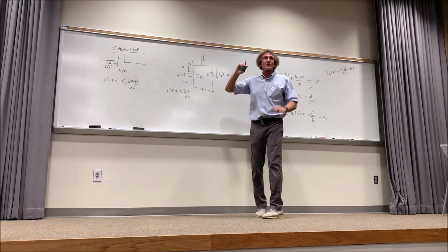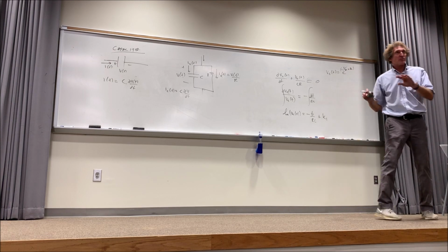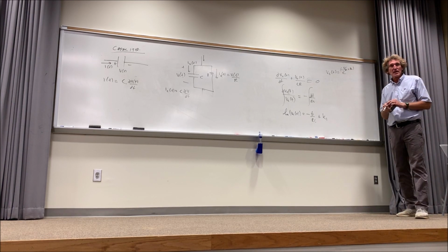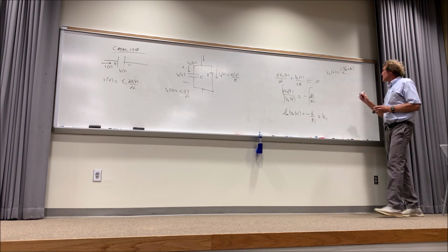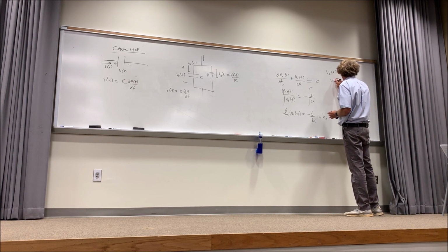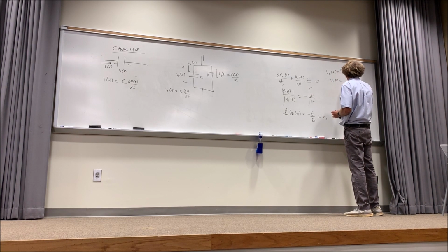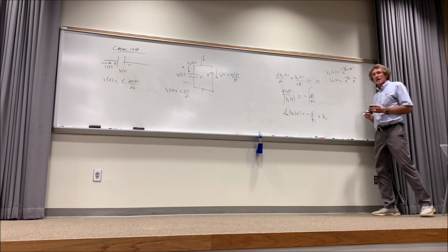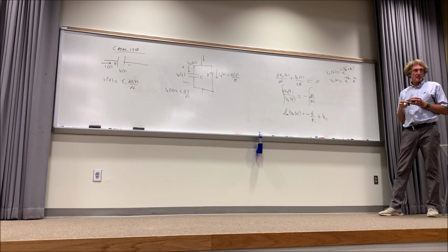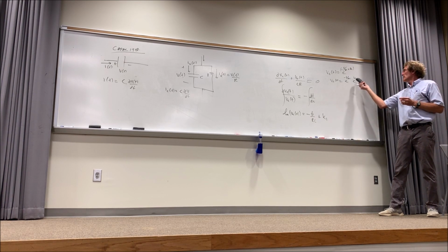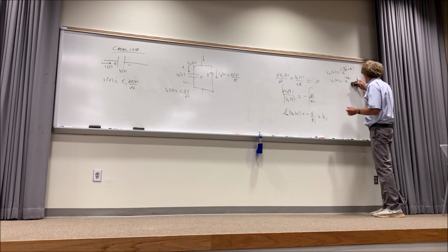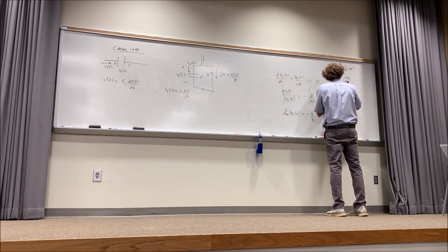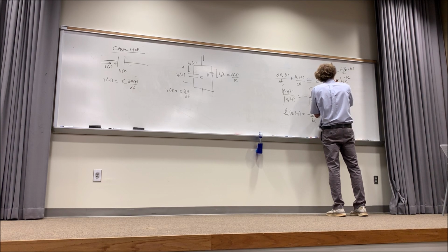And I'm not doing Laplace transforms. I'm not going to use crazy integrating factors. I'm going to keep it simple. Now, when I get down to this point, right here, I can break this out and just say this is really equal to VC of t is equal to e to the minus t over RC times e to the k. Do y'all agree with that? Just break it out. e to the AB is e to the A, e to the B, right? Well, e to the k, isn't that another constant? So I'm just going to call it V naught as my constant. And that's VC of t.